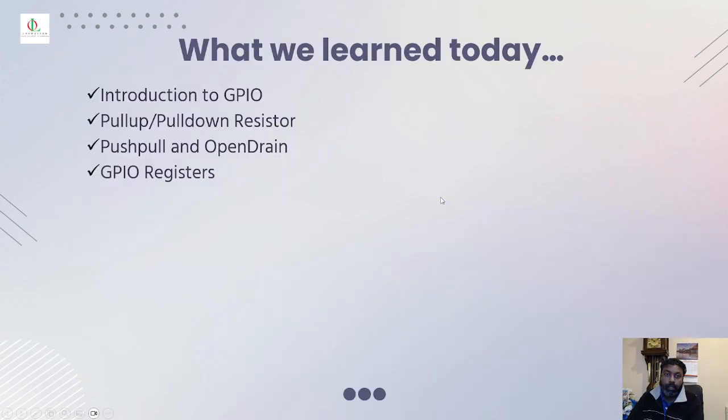So thank you for listening to me so far. What we learned today, we learned about all the GPIO, its introduction, how and where. You learned about its active low and active high, comparatively with LED and switch. And also you learned about pull up and pull down resistor, where it is used and what is its purpose. And also two types of output type configuration, the push pull and the open drain, where the output data can be read in two different forms. The push pull, it gets two states, 1 and 0. Open drain, it's 0 or high state, floating state.